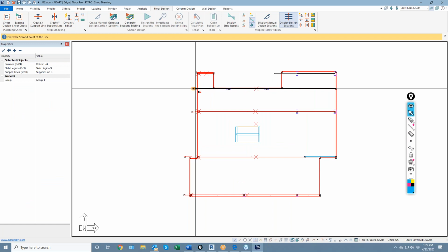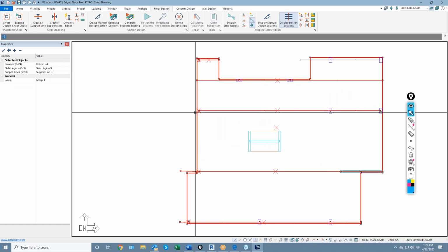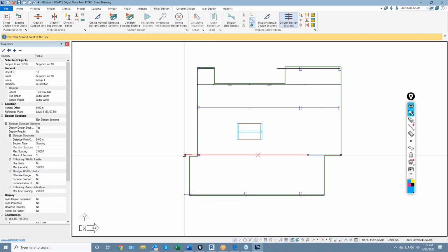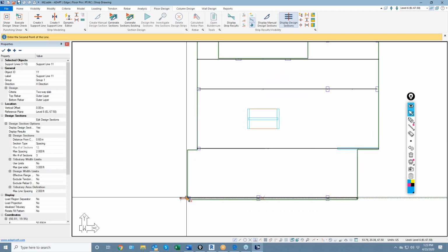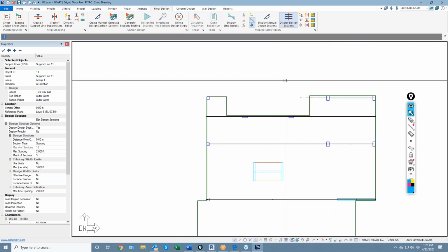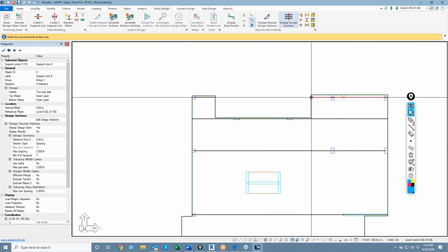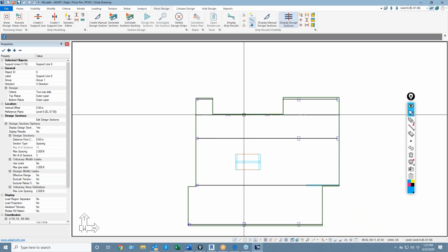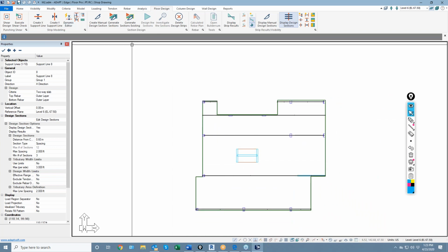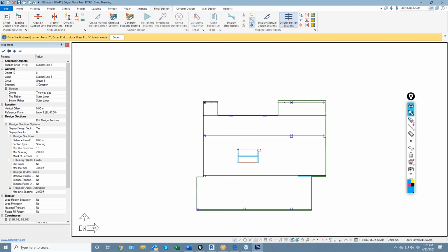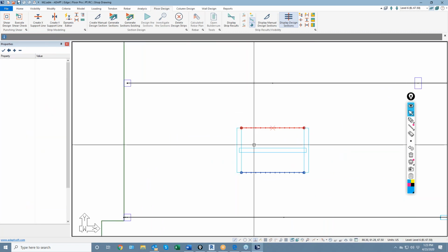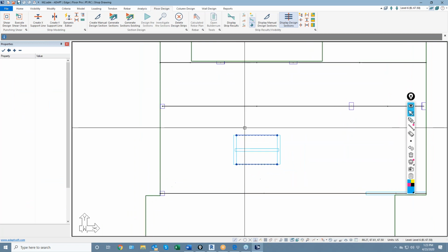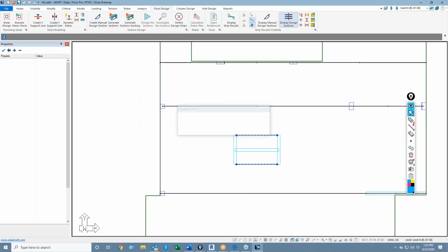And the more strips you have, the more design cuts you're going to have, which means you'll have a more refined breakout of results in the slab per the strip method. You'll be able to refine the number of design points, or data cuts rather, for that. So again, in this direction, we're going to use an X splitter, and I'll bound this opening off from the design cuts entering that area. And I'll generate my strips again.